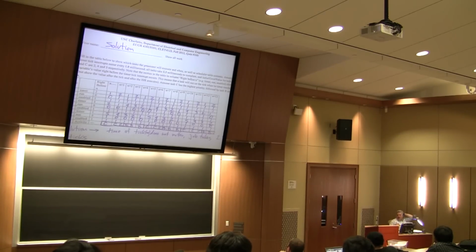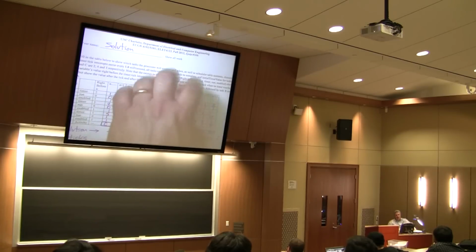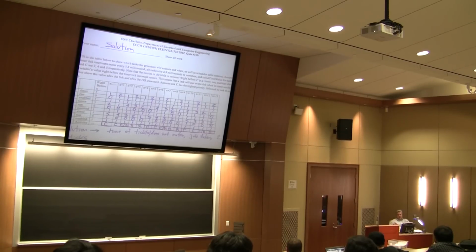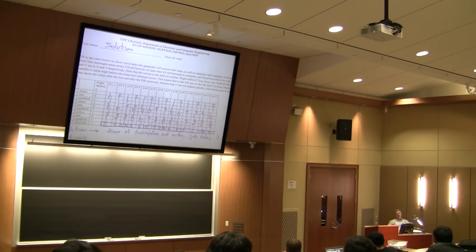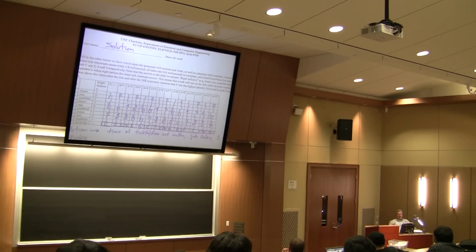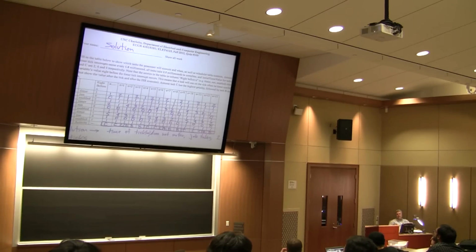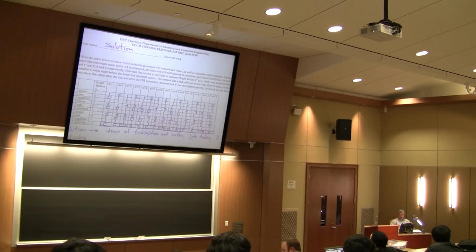So you never know when I might give another problem that looks just like this, where the processor is not overloaded. In fact, where the processor might be the other way around. It's 2.5 milliseconds for a timer tick, and each task takes 1.0 milliseconds. You never know when something like that will happen. For a quiz, perhaps. All right?